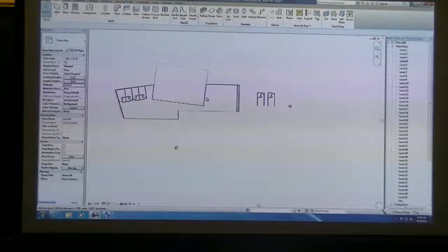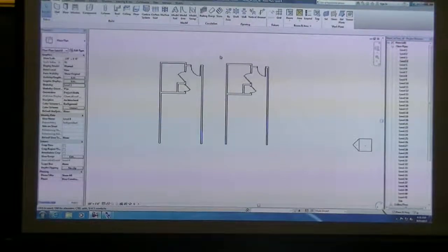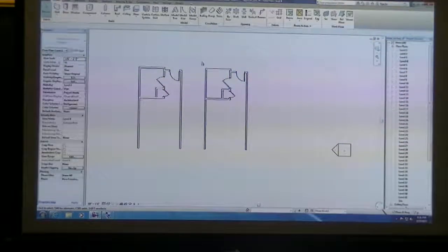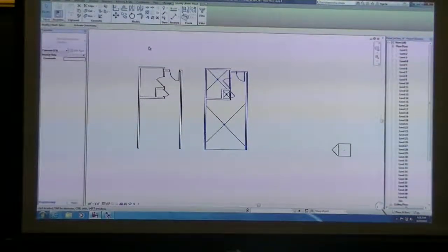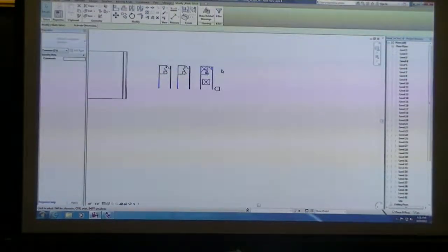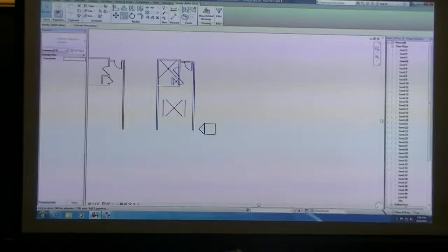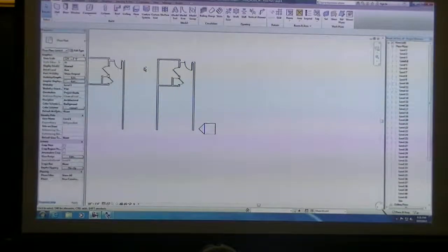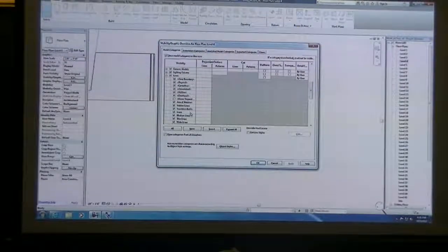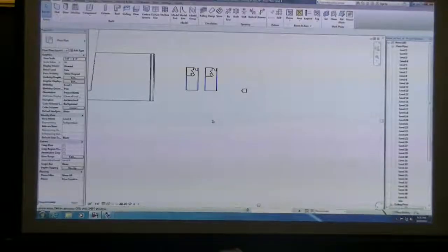So now what I can do is, I've got this hotel block, and let's say I wanted to start putting this repetitively all throughout at least my 4th floor plan that I'm working on. Some of you might just take what we've already modeled and copy it. And let's say I copy this a couple more times. Of course I didn't select my room separation line, so I need to turn that back on, so I'm going back into my visibility graphics and turning on room separation.